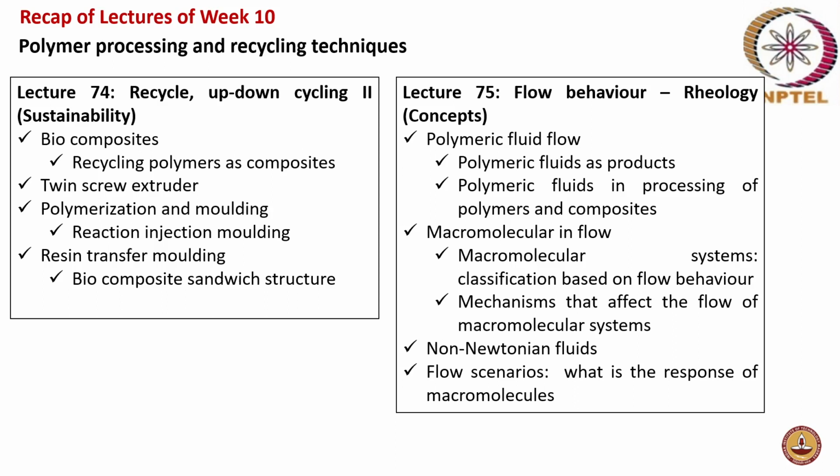And then the interaction with solvent, like your Brownian motion and your drag and friction and hydrodynamic interactions. So these were all discussed. And based on the flow scenario, what kind of response is to be considered in case of steady flow or unsteady flow, when fillers are present, and when polymer is pushed through a porous media. So depending on the scenario, the flow behavior and the response of the macromolecules vary. So these aspects were all discussed in the lecture on rheology.